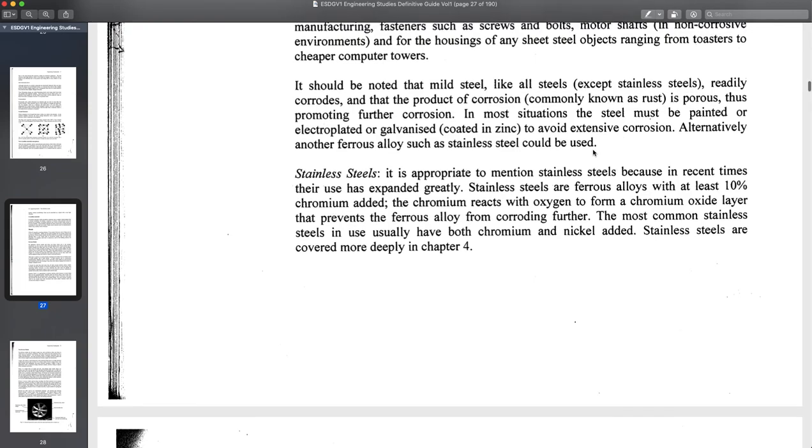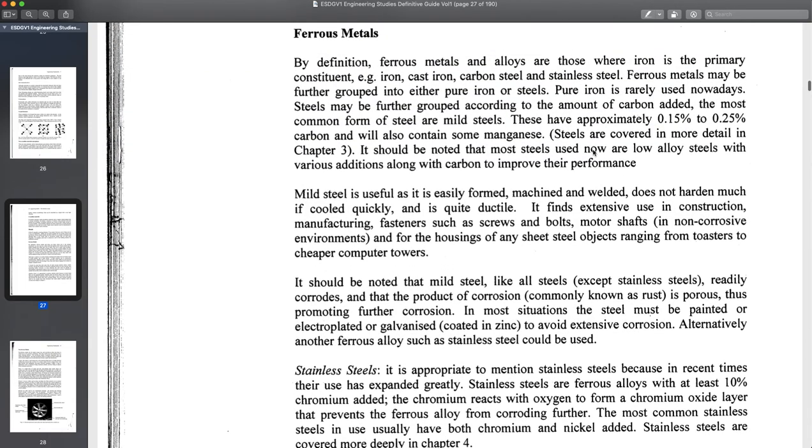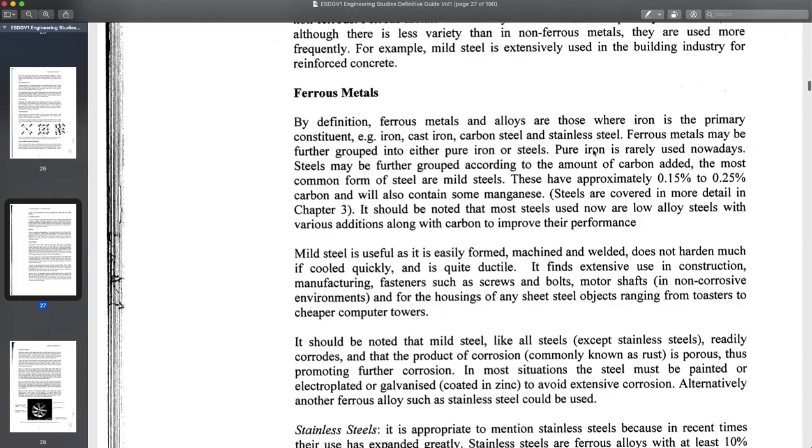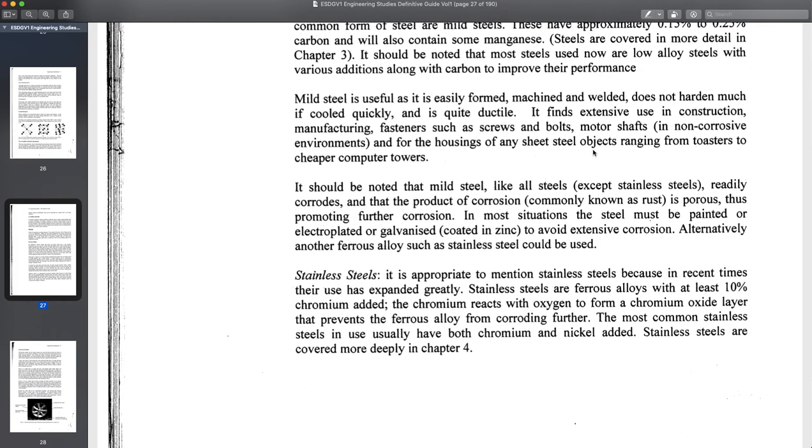The whole point here is that carbon content can vary really wildly. Steel stops getting stronger at about less than 1%. The reason we like cast iron is that at about 3 or 4%, I think about 4%, it casts the most easily. At 4%, it casts at the lowest temperature, so you need to heat it up less. And obviously if you have to build really big fires, a lower temperature could be good.